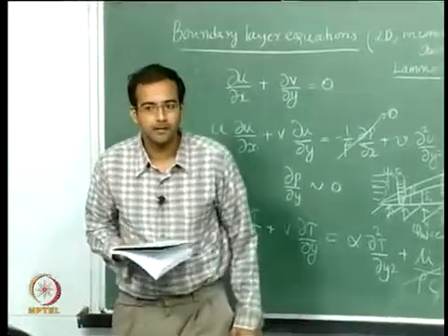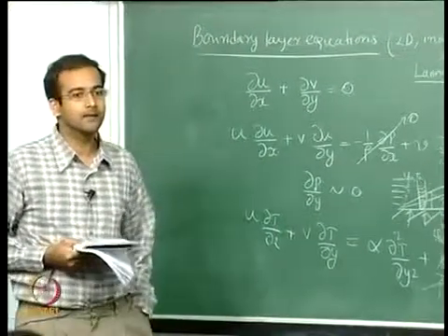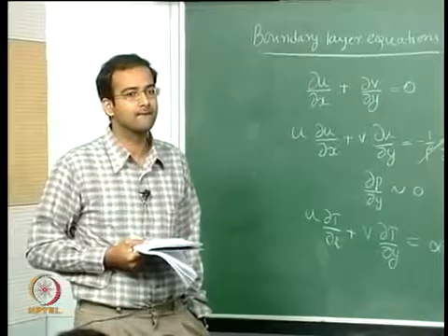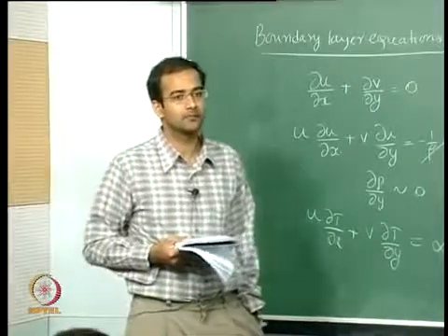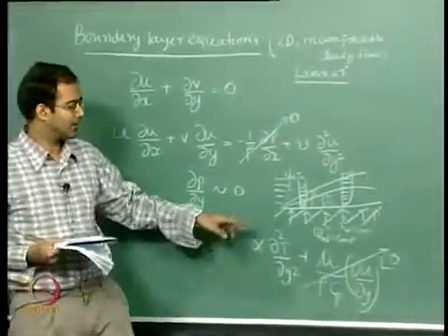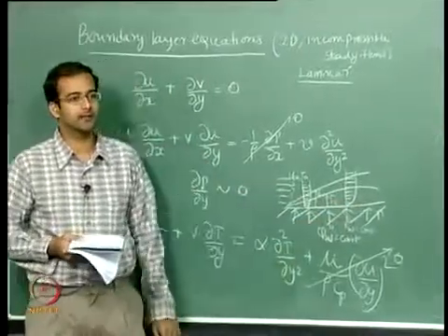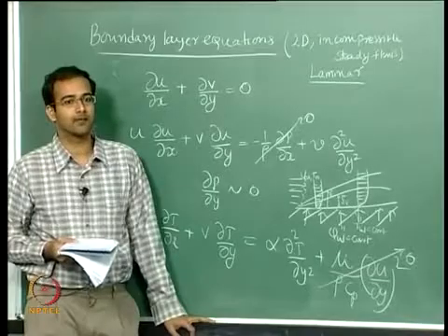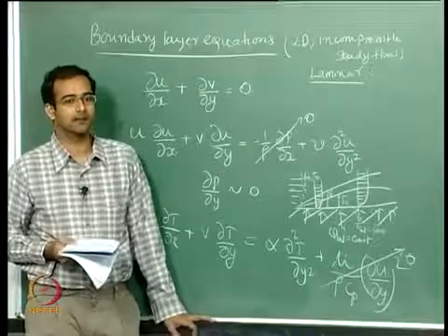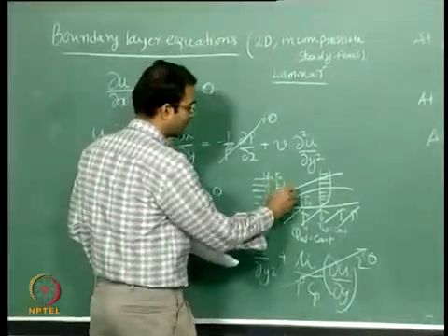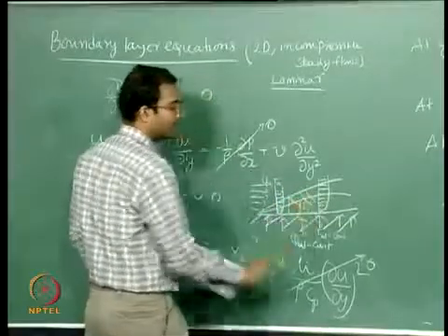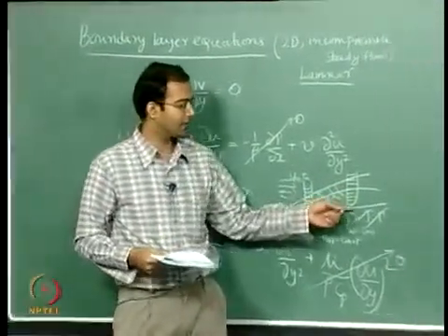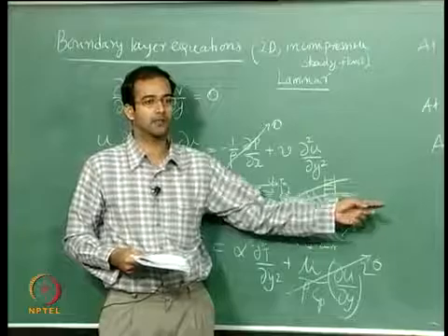Because the velocity close to the wall becomes zero. It's almost static. It's always 0. Always at the wall it is 0, but why should the gradient decrease? The boundary layer thickness keeps on increasing, and you have more flow which is entraining from outside. Therefore the profile becomes more and more gradual as you go down.